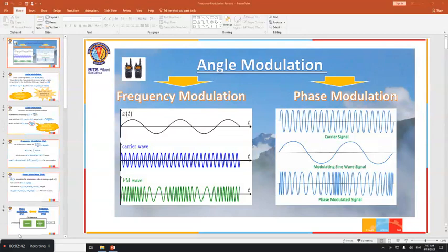So next, what? Amplitude we have exploited now. The amplitude of the carrier we have used to embed your message signal. Now it is giving me a problem. It is highly susceptible to noise. What next? Next is frequency. A carrier wave has amplitude and also it has frequency, right? When you vary the amplitude of a carrier wave, it becomes amplitude modulation. At that time frequency remains the same. Only amplitude varies. And you know that because of noise, that amplitude may get disturbed and you lose your message signal.